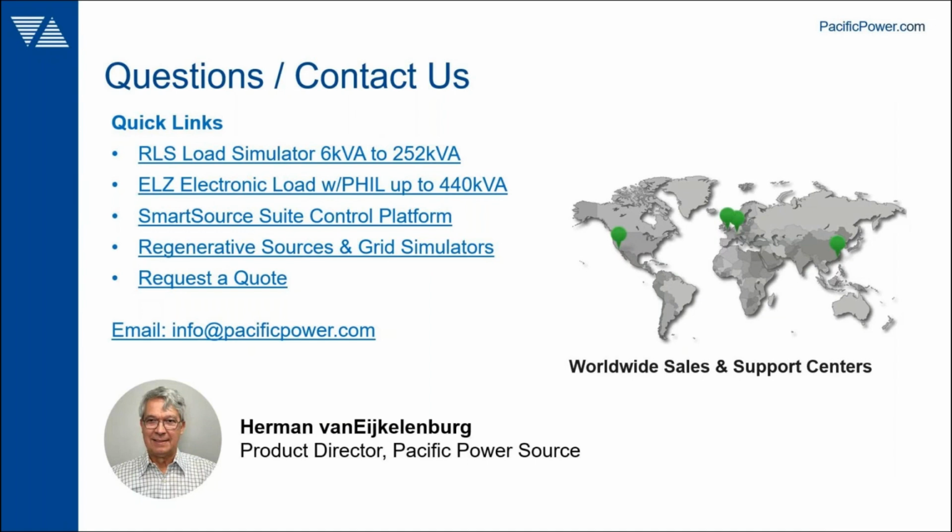Perfect. And what is the downside of using a regenerative versus a non-regenerative load? Well, they tend to be a little more expensive for the same power level typically because of the bidirectional nature. So generally, the acquisition cost can be a little higher than a conventional dissipative load. But generally, the cost savings and energy recovery tend to nullify that over a relatively short period of time.